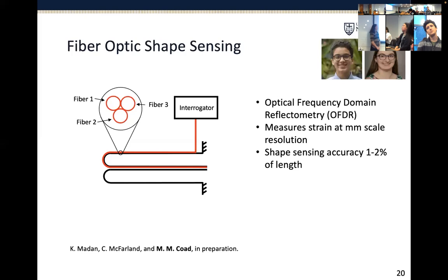if we can't figure out a way to constrain this so that it doesn't rotate along the length of it. Okay, and then to get the global shape? So you add up the curvature. We're assuming locally circular between every sensor measurement along the length, we assume that it bends with constant curvature to calculate the full shape.